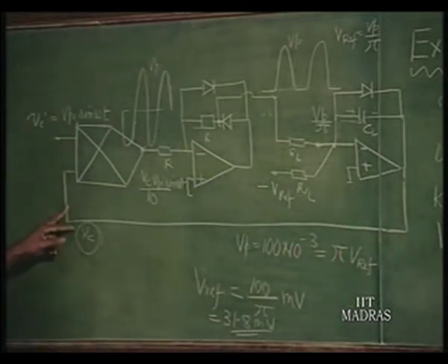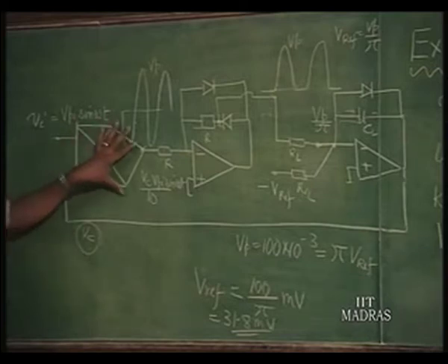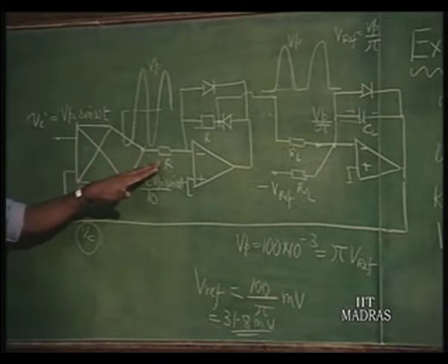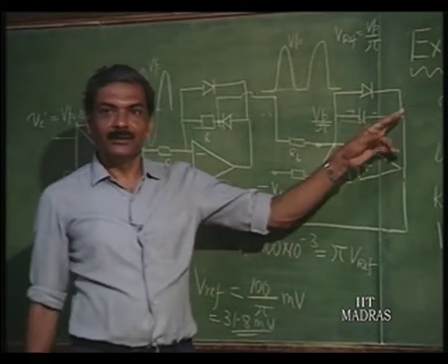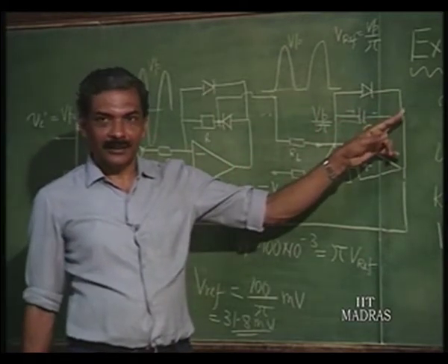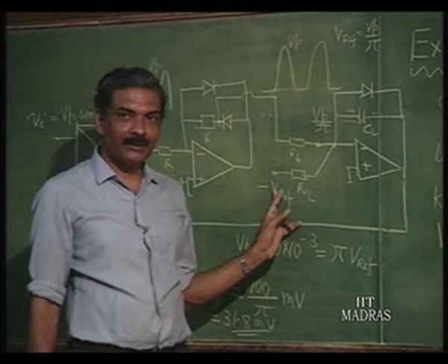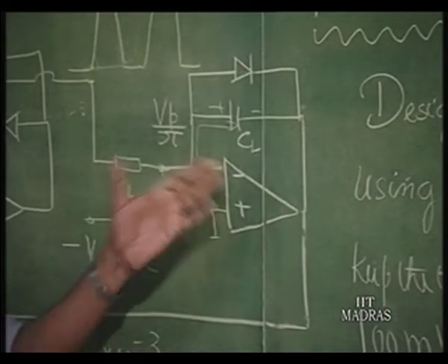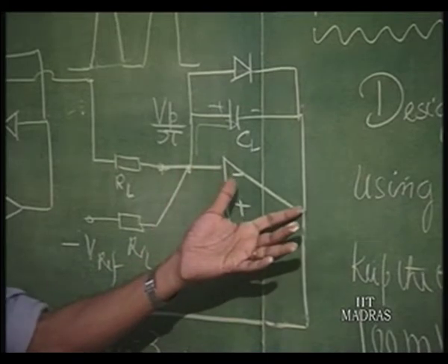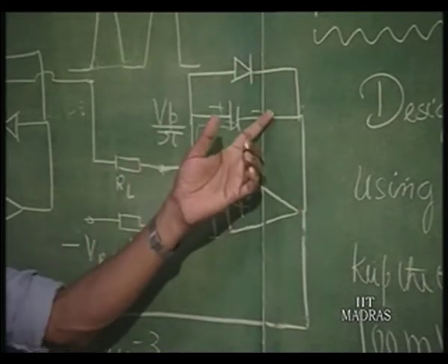If that is plus 10 volts, let us say, then this has the highest gain at that time. So, output will come. So, there is no question of this ever going negative here as long as this is applied. So, even the accidental situation of this going to negative saturation is prevented by this, that is all.